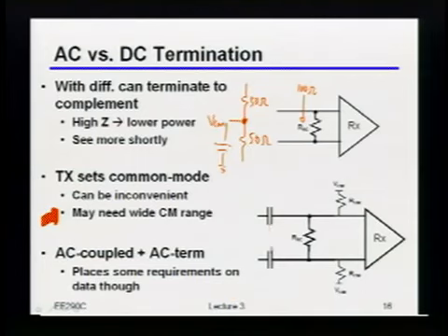So indeed, decoupling things like this is pretty nice, but of course it places some requirements on the signal, or rather the data itself, because these AC coupling caps mean you lose things at DC. If you've ever heard the term baseline wander or DC drift, that's associated with these AC coupling capacitors. Again, we'll talk a little bit more later on about the exact implications of that and how you deal with it. But just keep in mind that you can't always throw those AC coupling caps in.